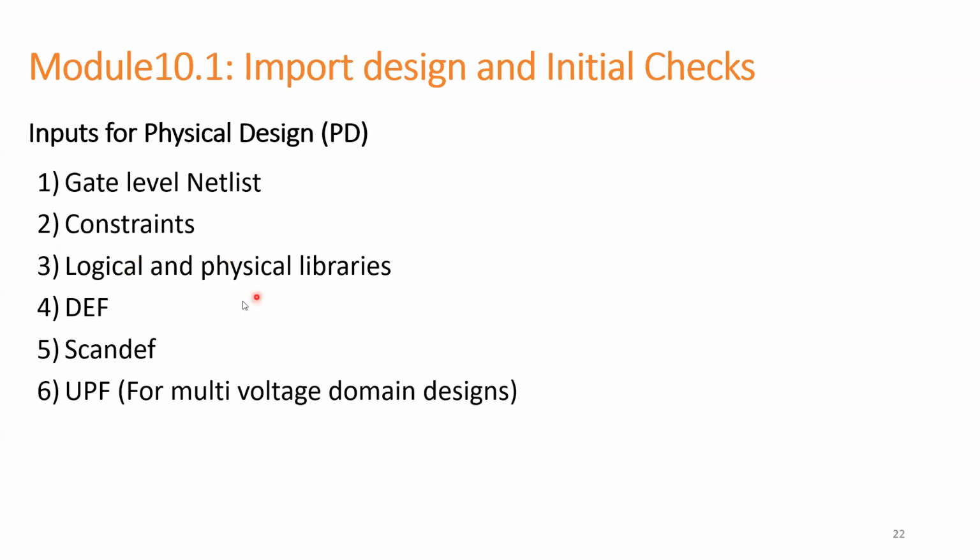Scan DEF: for the scan chain there will be a scan DEF, and it will be given by the synthesis team only. UPF is required for multi-voltage designs. In the UPF, all the power and ground information will be given. The supply net connections will be given, supply net information, supply set information. If there are any level shifters, power switches, or multi-power domains, all that information will be given in UPF.